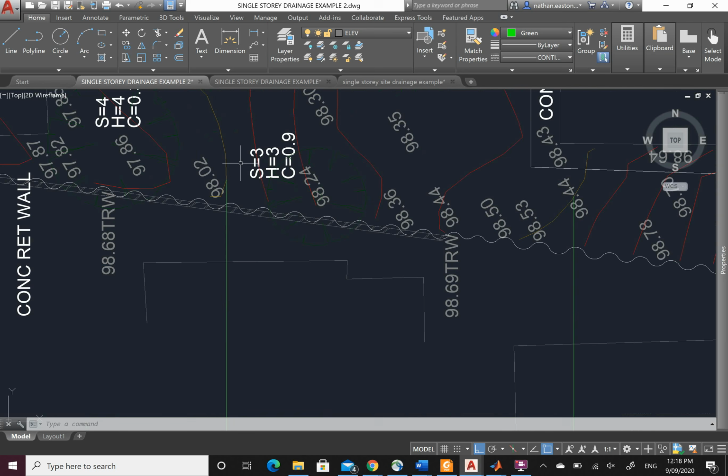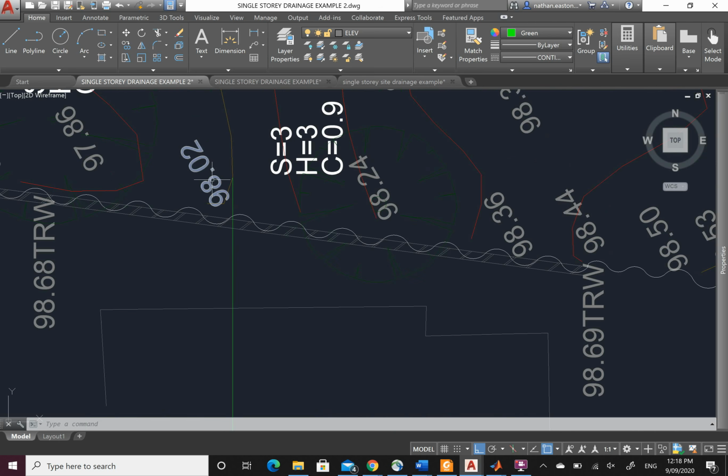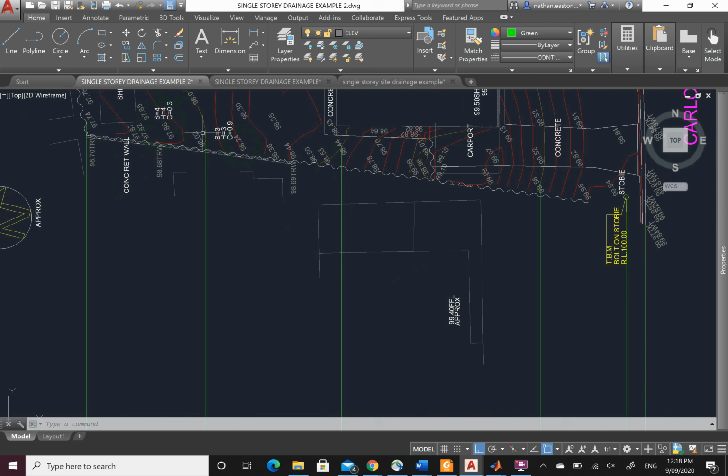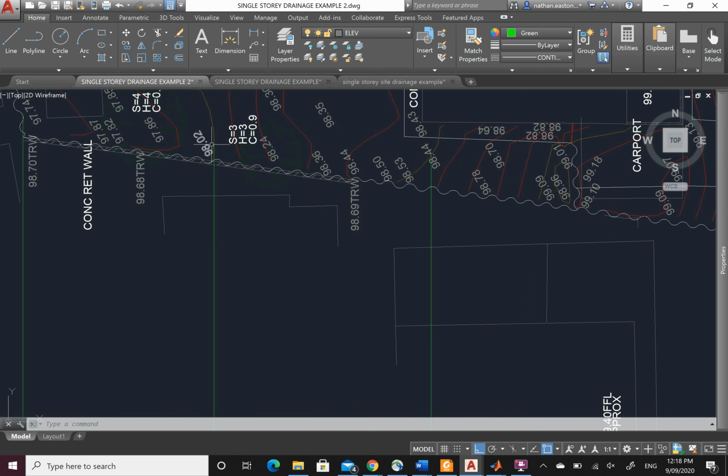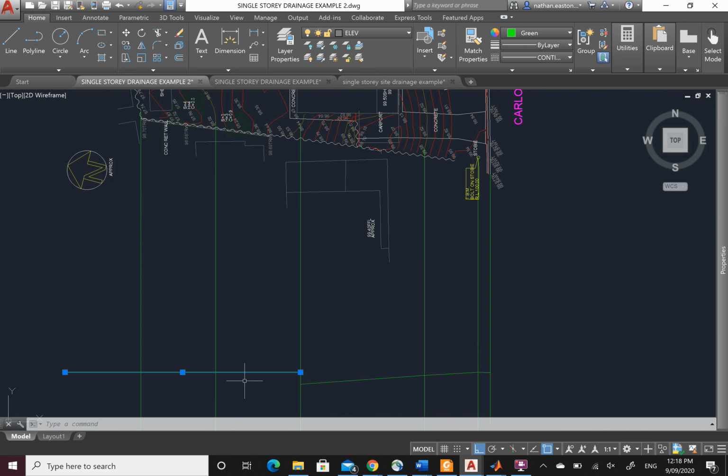Now what happens here? Well, we keep going. So further down, to get this to 100, always bring it back up to this reference level. What's that? 1.98. So copy down 1980.